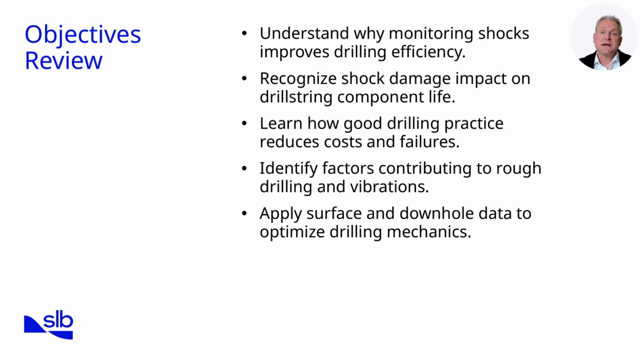Let's now review the key learning objectives for this sub-module and tie them back to the material we've covered. We began by asking why shocks must be monitored. We saw that shocks waste energy, reduce drilling efficiency, and accelerate wear on drill string components. Next, we examined how shock damage accumulates, shortening tool life even when no outright failure is visible, and why inspection must account for shock history.